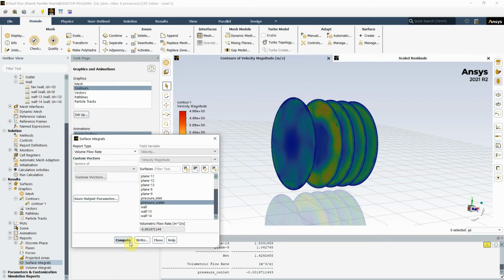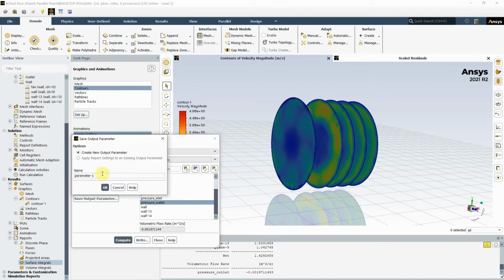Obviously we can make that a lot faster, a lot more air going through, by changing the RPM or changing the blade. But because the number of blades is fixed and the RPM is fixed, the angle of the blades will have an influence on how much air is flowing through. Also, the design of the blade will also have an impact on how much air is going through. So sometimes it's maybe important to save this as an output parameter, so volumetric flow rate.